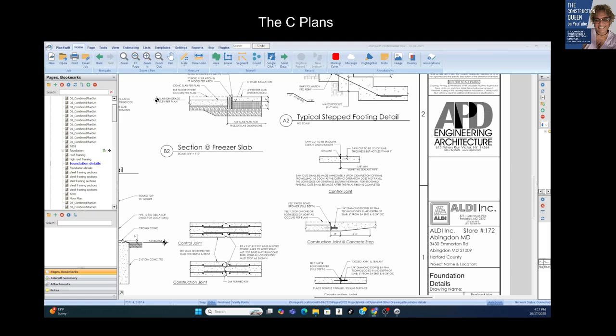Anytime there's a discrepancy, say you're the concrete contractor, or you're the framer, and you're noticing a discrepancy in where the HVAC is going, where the framing is going, well, you can go to the actual roof plan itself, and those should match up. And if they don't match up, that's a point of contention. That's something you tell somebody.